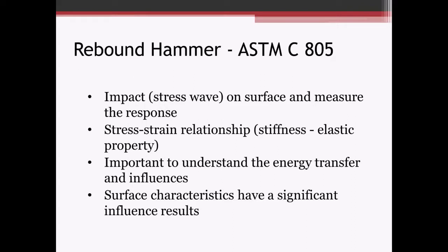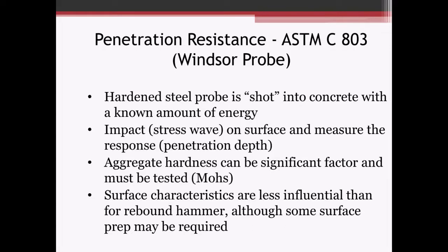So you've got a stress wave impacting the surface, measuring the response. Maybe it's the velocity of that hammer coming back up. Maybe it's just the general stiffness of the concrete, with how far that hammer rebounds back. Again, it's really important to understand that energy transfer and what happens, not just at the concrete surface, but also below the surface. And again, those surface characteristics could have a pretty big impact on what your rebound number is.